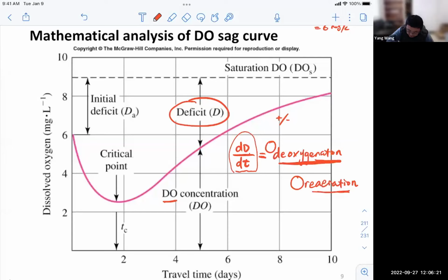It should be positive, but the reason is, let's think of extremes. If you have faster deoxygenation, are you going to have a higher deficit or lower deficit? If you have more deoxygenation, then I guess you would have a higher deficit. Yes, that's right. So that's why this term should be positive.